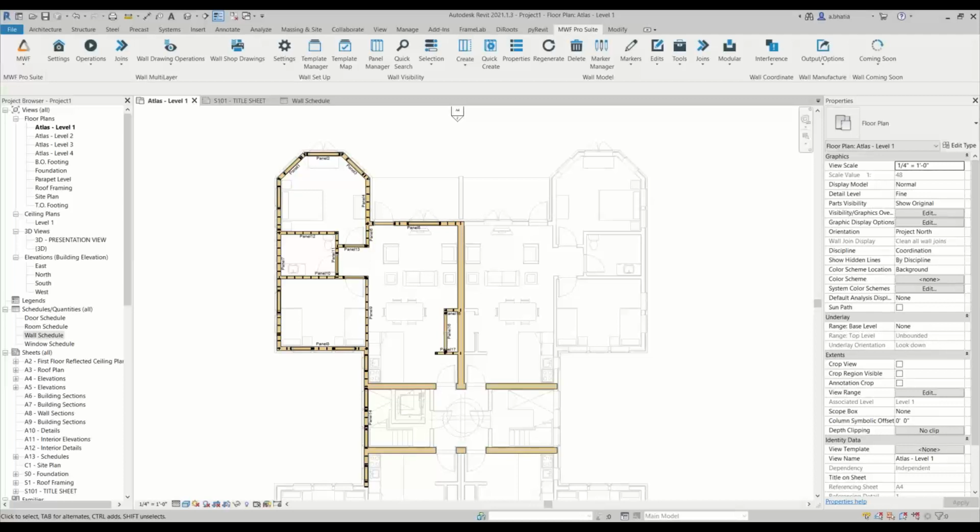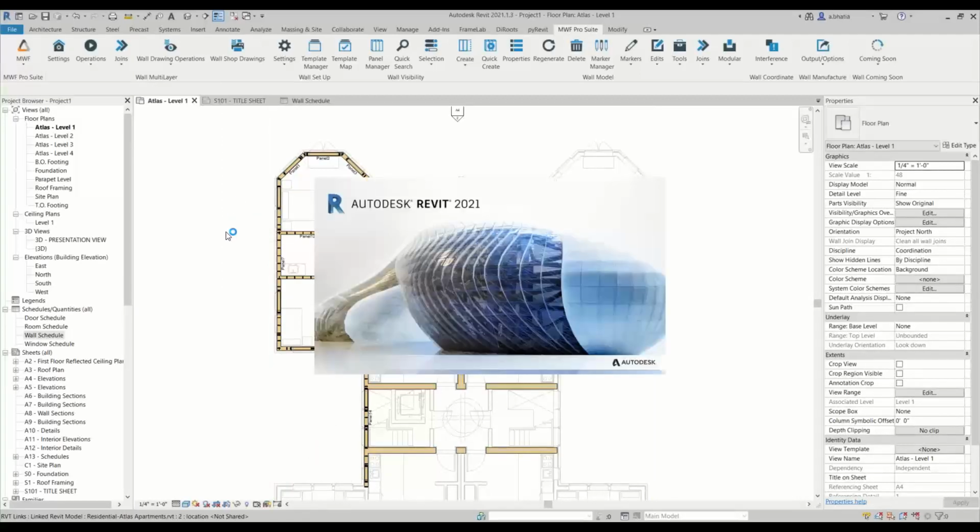Okay. Yeah, I was wondering if you can actually show, like, if the wall changes, how it affects the new wall you copied. Sure. So you mean in the link if the wall gets moved? Right. Okay. So let me actually open another Revit session for that, because if I open the same Revit session, it kind of unlinks the current link. So I'll just open another Revit session for that.